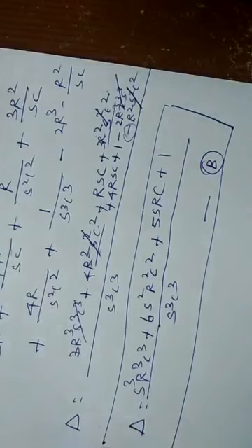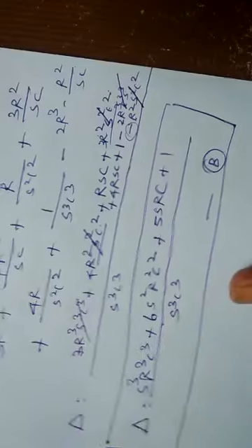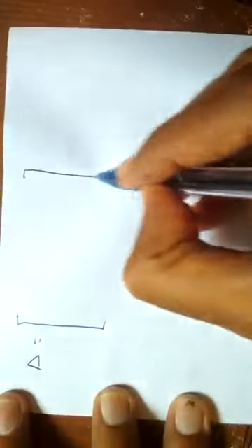From this equation, we have to find especially the individual current I3, as we have discussed in the earlier part of this derivation. So I3 is the final current from which only you will be able to get the feedback potential Vf. So directly we can solve I3, no need to solve I1, I2, because I3 is the final current. To solve I3, the same matrix can be used, but with a slight change: the third column must be the values of the potentials we have achieved.